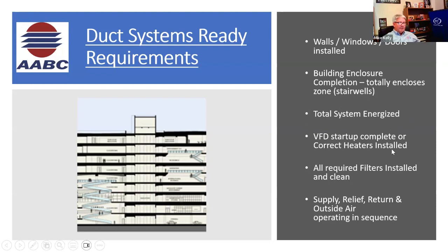VFD started, completed, correct heaters installed. This VFD startup complete is very important nowadays. Don't overlook it. Oh, it's fine. They started it up. It's good. All too often, these VFDs nowadays are so complex with VFD startup that they can be limited on RPM. I've seen them where the VFD is set up and it will only allow the motor to run at 80%, 90%. Well, it's running at 60 hertz, but it's only running at 1580 RPM, not 1750. Well, it says it's at 60 hertz. Well, the VFD is this voodoo thing out there nowadays. It absolutely needs to be started up by someone competent.